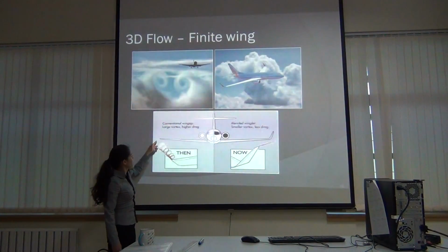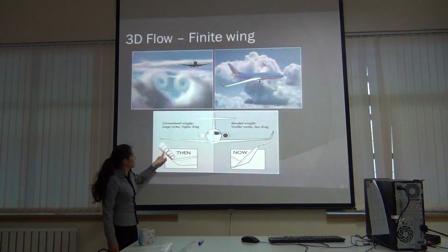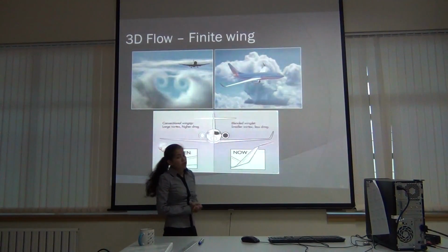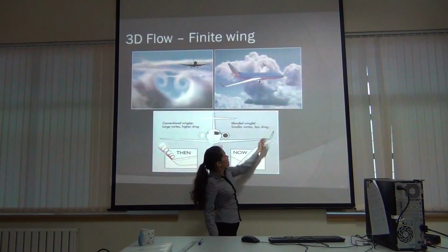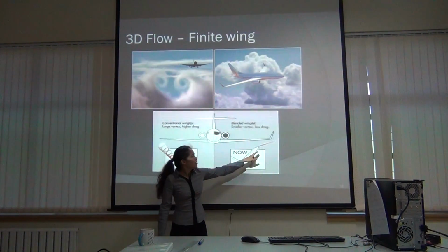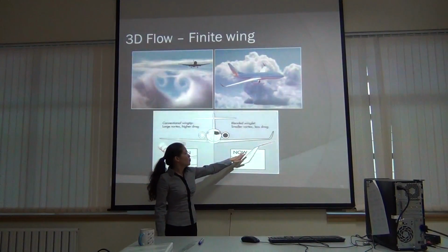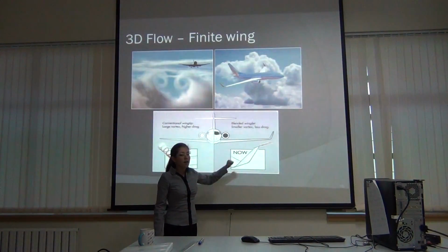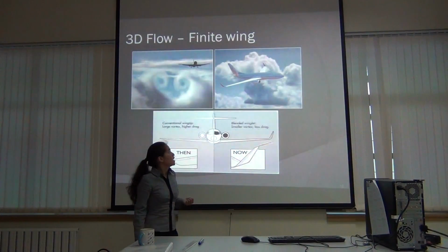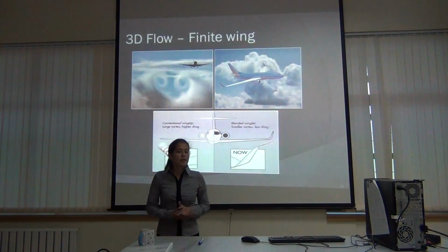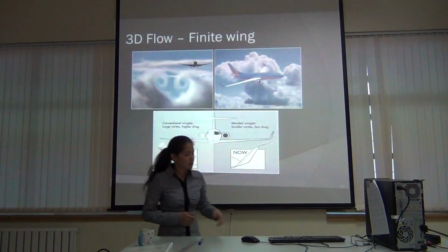And this makes this effect of spiraling. And this is called vortices. And that is why aircraft use winglets. This decreases vortex effect drastically. And when the vortices are small, this decreases drag as well. And that is why winglets are used in commercial airliners to make them more efficient.